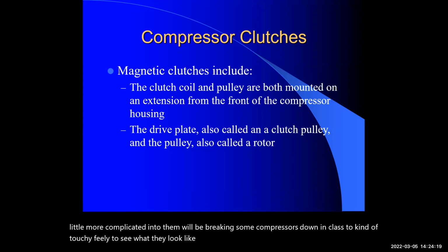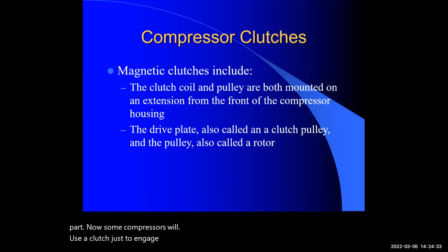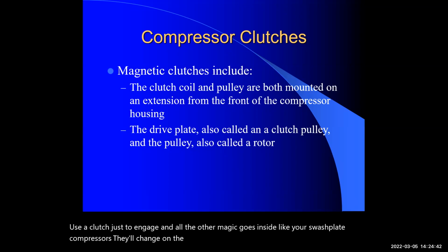The other thing I want to bring to your attention to is compressor clutches. Now, compressor clutches is what starts the engagement part. Now, some compressors will use a clutch just to engage, and all the other magic goes inside, like your swash plate compressors. They'll change on the load value.